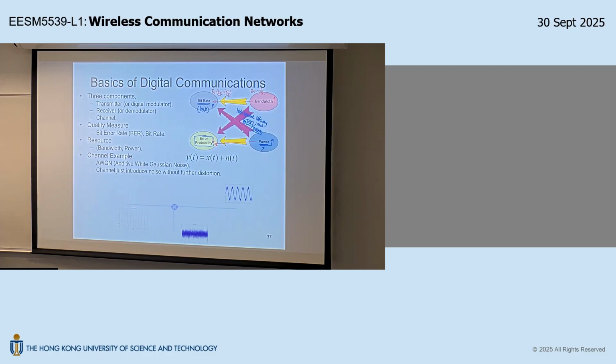Okay? Because we talk about high carrier frequency, the propagation physics is line of sight. You need to see the transmitter before you can receive the signal. For satellite application, that's fine. That's not too much of a problem, right? So at 60 gigahertz, you have plenty of bandwidth. Is that okay? So because of that, in this particular situation, this is less expensive, this is more expensive. So you want to reduce this at the expense of this.